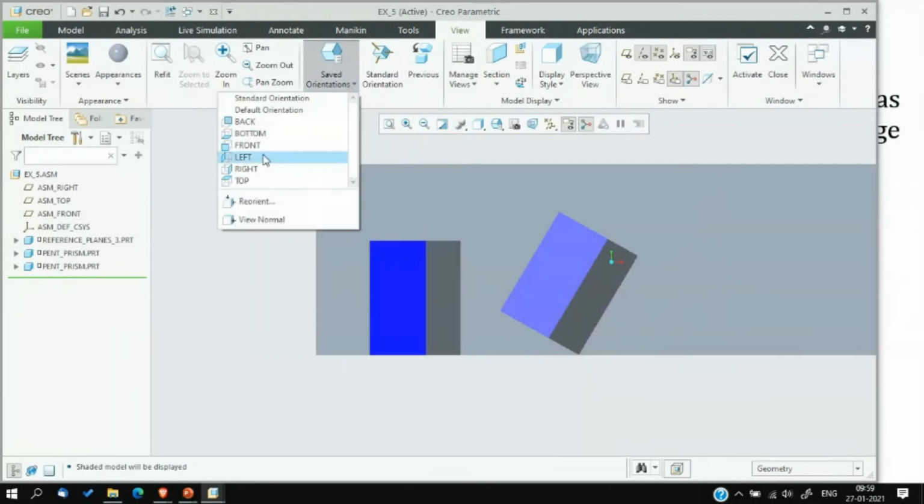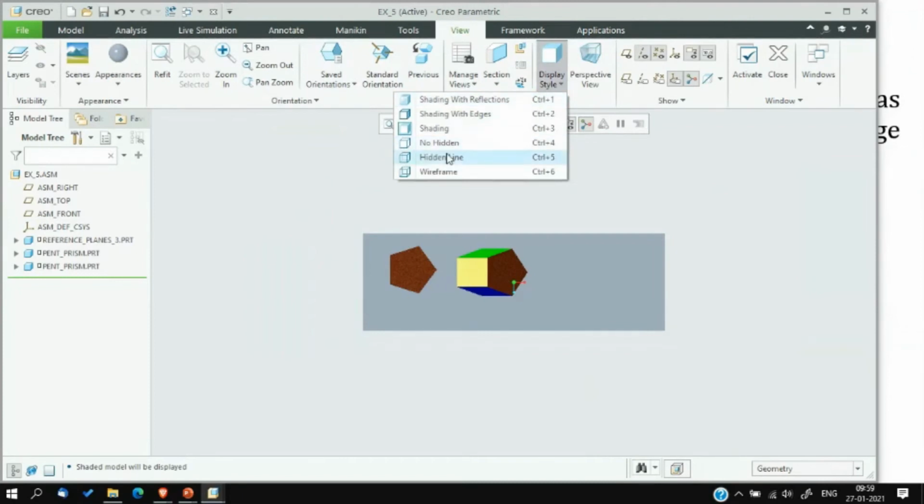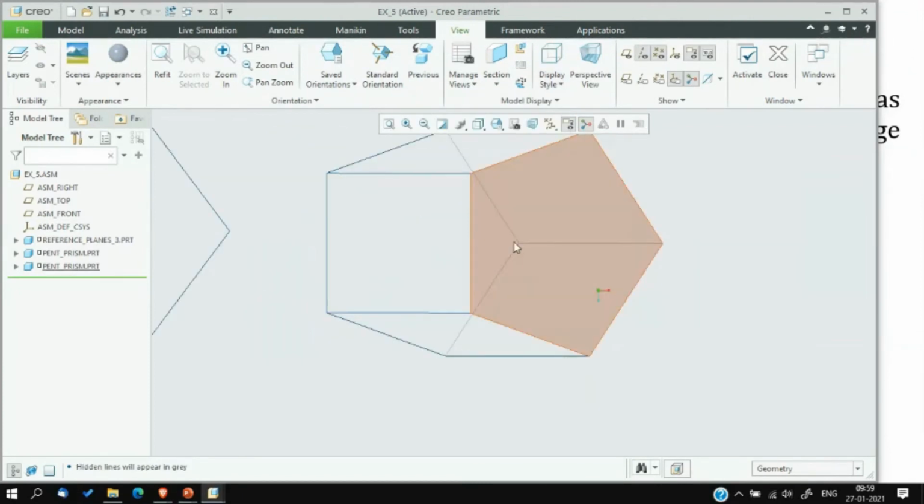In the top view, there will be three invisible edges starting from a single corner. Whichever edges start from the bottommost corner will not be visible in the top view. So you can identify from the front view which is the bottommost point, the bottommost corner.